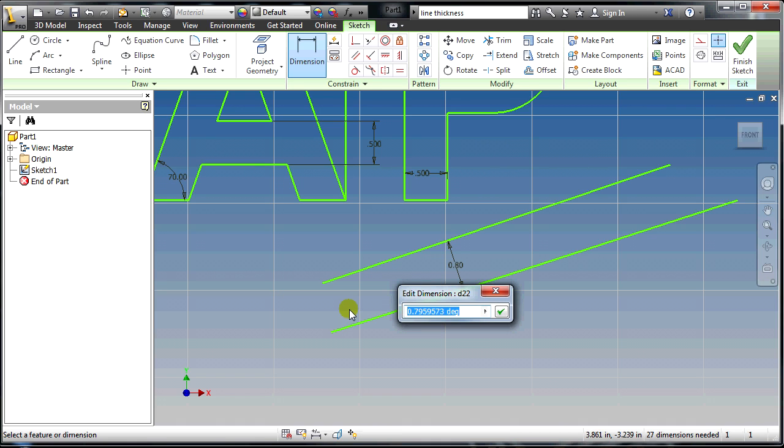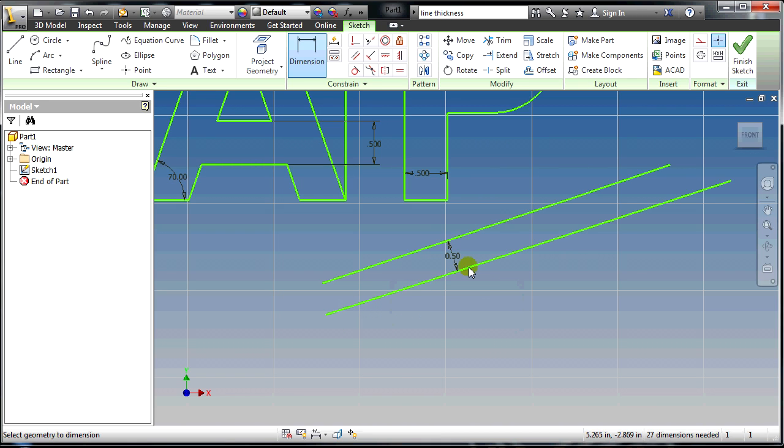So if I can say 0.5 and it'll look 0.5, but you can see that these are further apart than these are. And even though these look parallel, that's 0.5 degrees apart, not 0.5 inches, which is worlds apart. It's two completely different things. So just be careful. Be aware of what you're doing and what you're building.